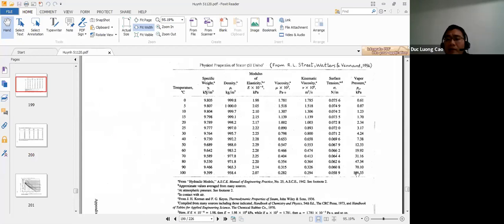And if the last column is the pressure, the first one will be the boiling temperature. First and the last. For example, if you have the temperature of water, the vapor pressure is the last one. If you have water at this pressure and you want to find the boiling temperature, it's the first column. First and last.